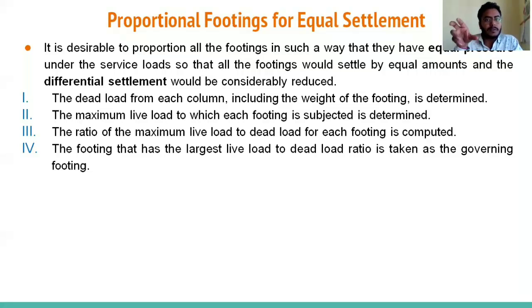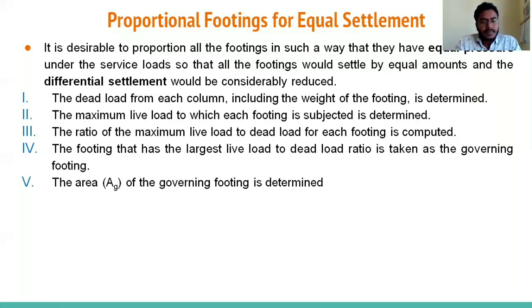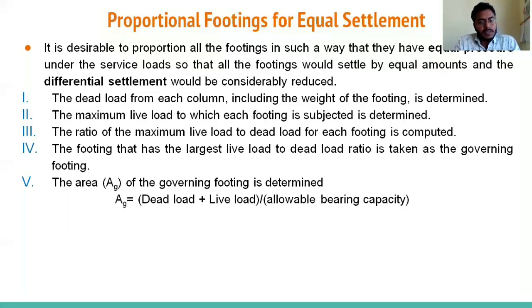You have to remember that. From the governing footing, we decide the area, and then we distribute the pressure to all the columns or footings, right?